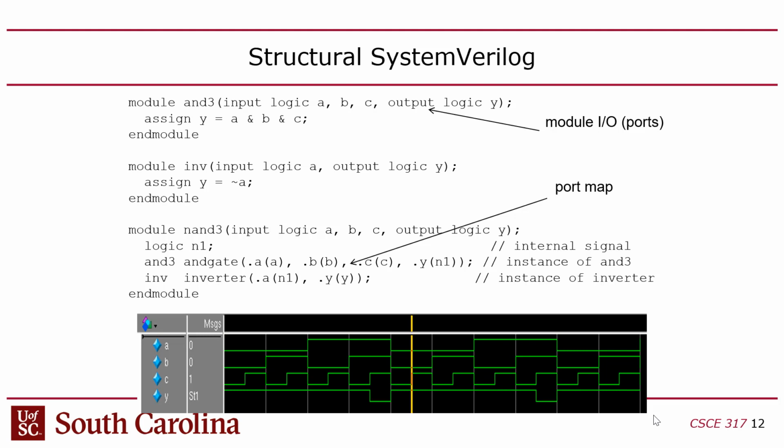Maybe it would be ideally. I guess maybe in principle it would be. But with all the overhead of JTAG and all the other stuff that has to happen, I think in practice it's not possible. You can't do real-time data collection at 50 megahertz, and certainly not if you had 200 or 400 megahertz, right? You guys with me? So I'll show you how to use Signal Tap next lecture.